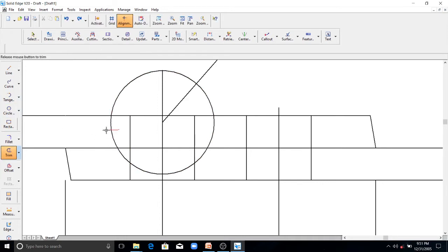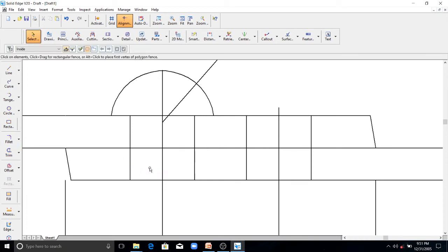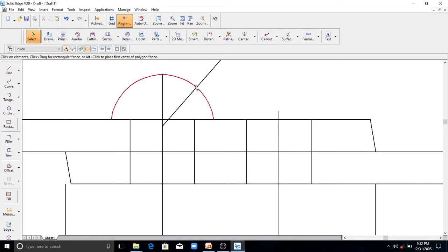So we need the center. Similarly, you have to draw the bottom portion of the snap head here. No need to again draw the snap height of the rivet and bisect those lines for the radius. Instead, you just measure the distance from this line to the center, and give the same distance at the bottom to get the new center for drawing the radius of the bottom portion of the snap head, as explained in the previous videos.